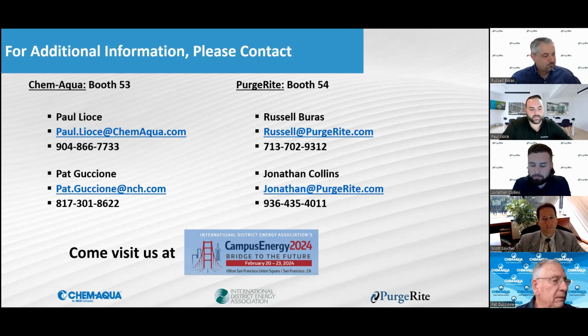Yeah, then on that one, I'd go a little bit more just reviewing those design issues. Do you have a lot of chillers that sit stagnant, that when they do come online, add to that bio load? Do you have a lot of dead legs that are contributing to that? So, even if you do get it clean, it's ultimately finding that root cause. If it was just poor treatment, then it was poor treatment. But if it's a design issue, it's then looking at it from that standpoint as well.